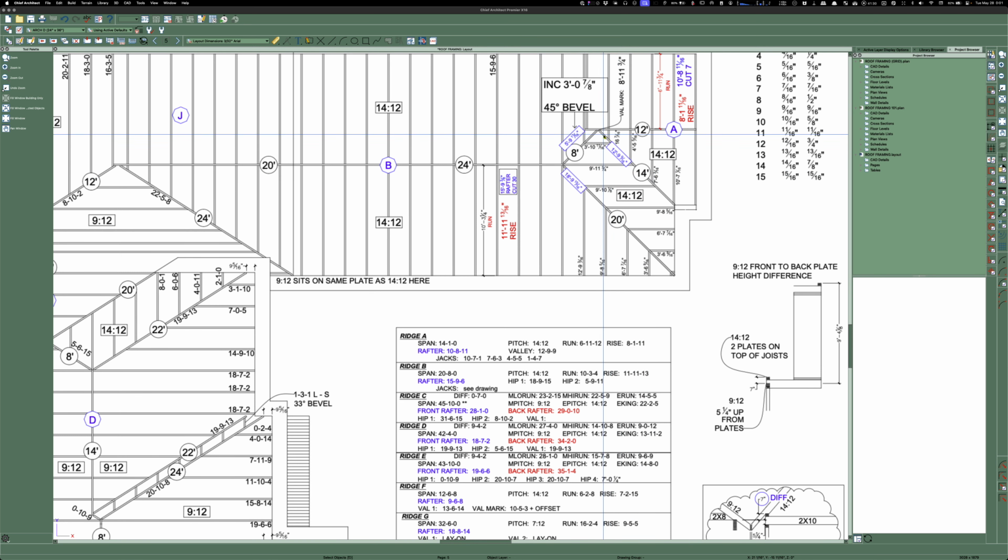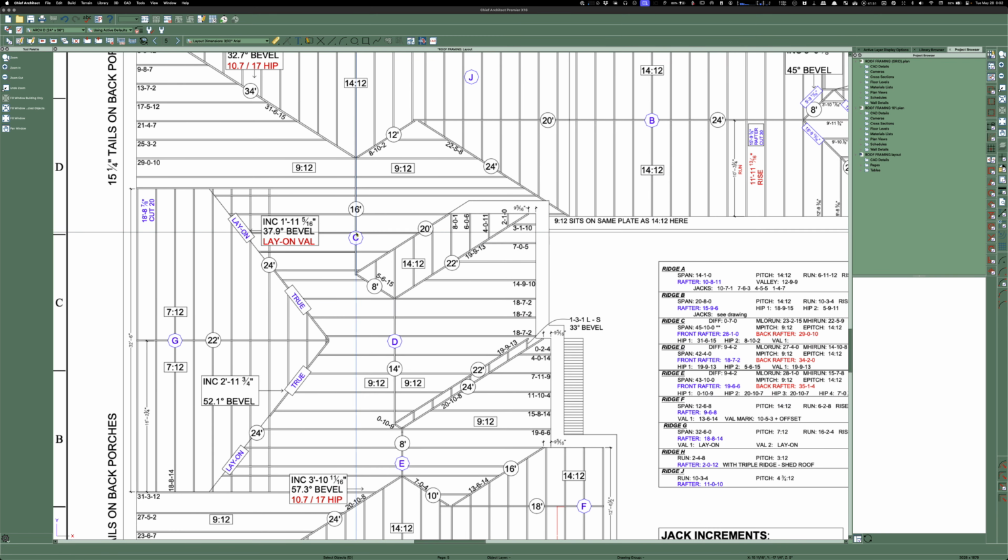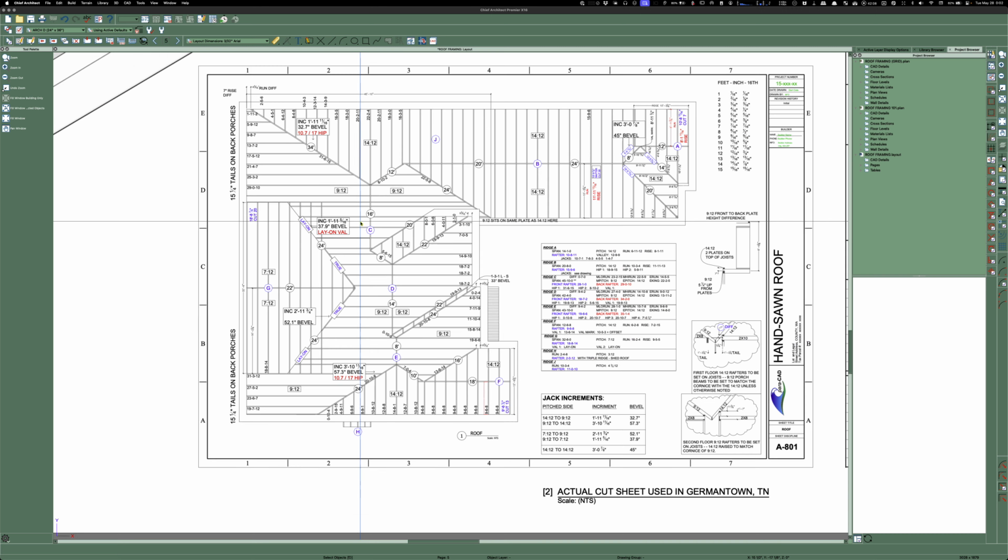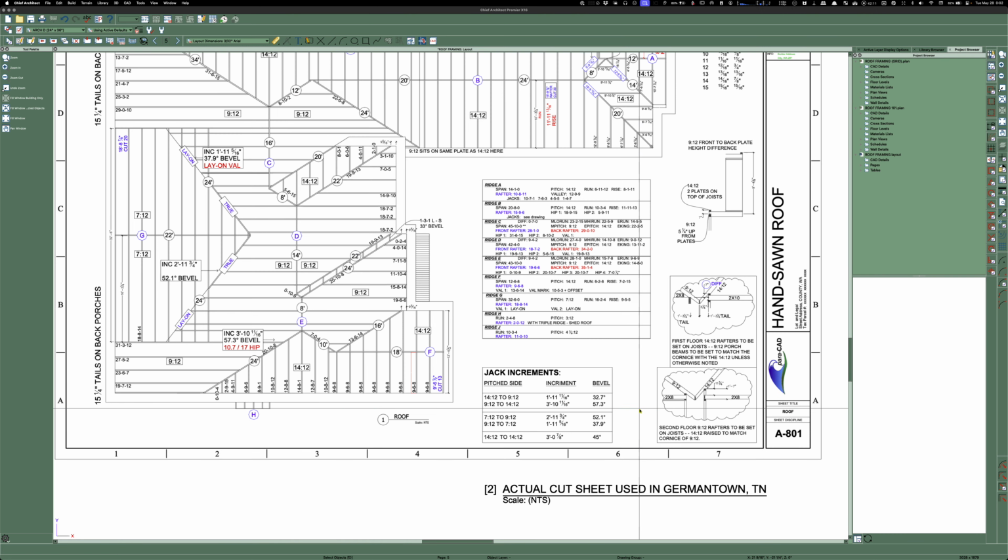Then this circle one was when I did the takeoff. I would, as I'm doing this, I'd say, well, it's going to be, where did I have the ridge here? I don't even know if I measured the ridges. I just knew that I needed a 12-footer here, because you can just count the layouts, or you can pull a dimension with your computer. I don't think I've ever cut a ridge on the ground and sent it up there, unless it's butting into an already existing layout. Because typically I like to leave those ridges a little wild, so that once they're in, they can be cut. But I have to think about that. It's been a while. I'm sure you could do it.